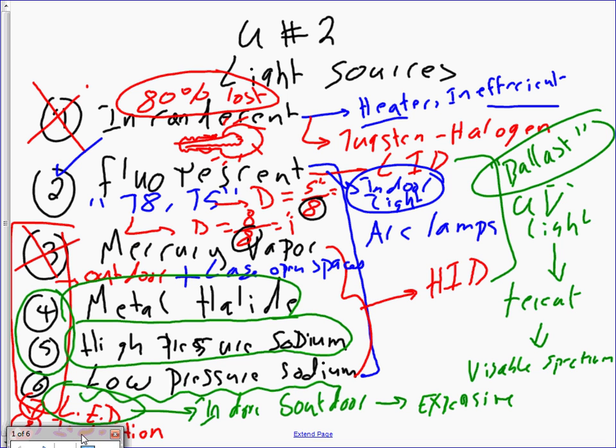And just to summarize, guys, there are two major types of lights. One is non-arcing, that's the incandescent light, no arc. The other one is arcing: fluorescent and high intensity discharge, right? The arcing has two types. One, low intensity discharge, fluorescent. The other one is high intensity discharge. These are the mercury, metal halide, and high pressure sodium.